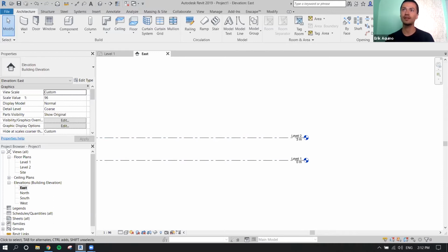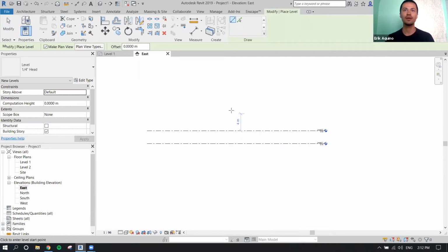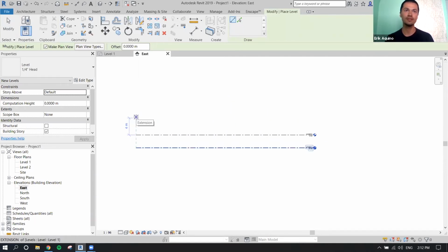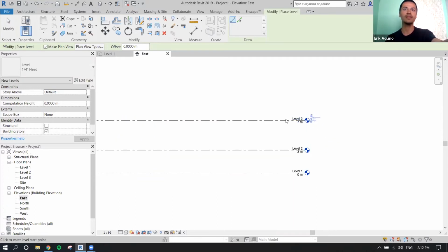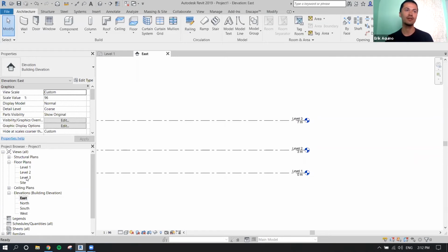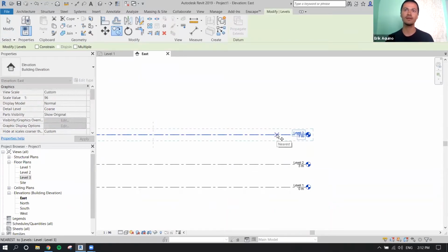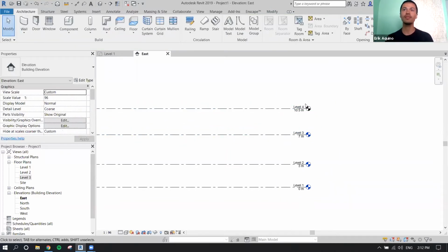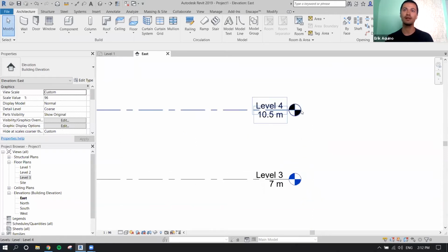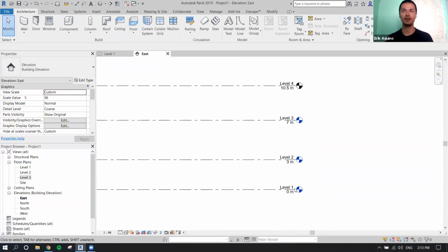If I were to select my level here at the architecture tab and datum section and create my new level with a 2-click process, one to establish the start, the second to end the level, you'll see that in my project browser, I've created a new reference level, level 3 associated with this one. If you were to copy a level, however, if I type CC to copy, click and create a new level, this bubble is colored black versus the other three, which are blue.